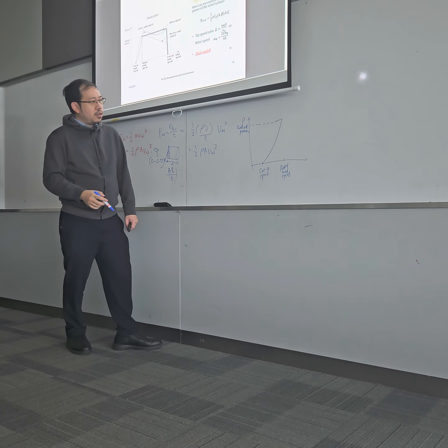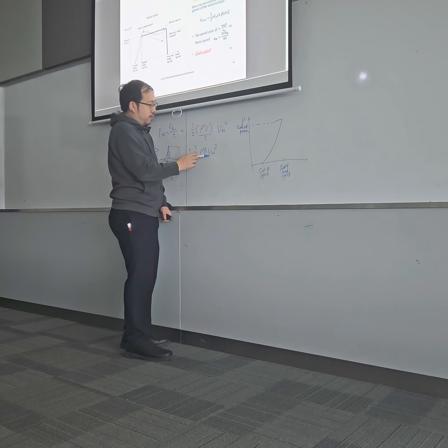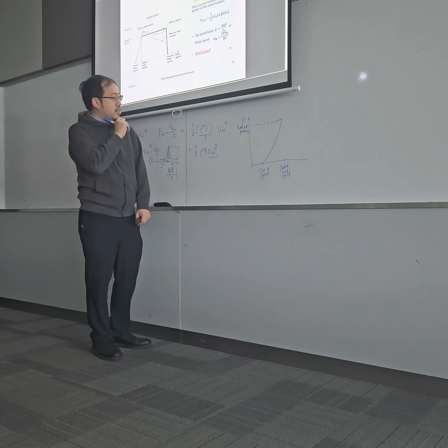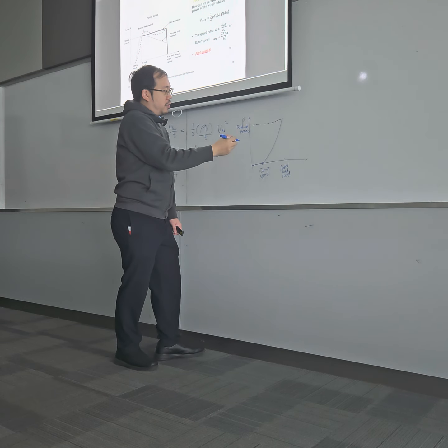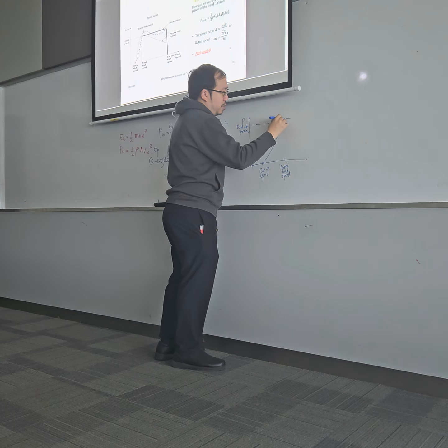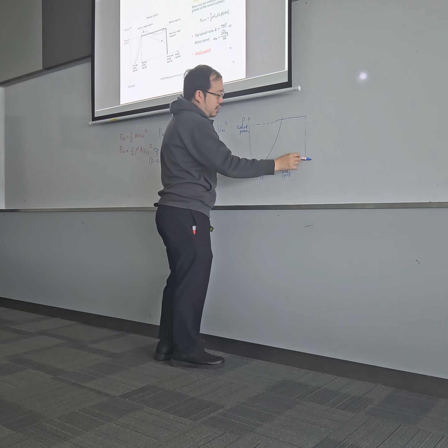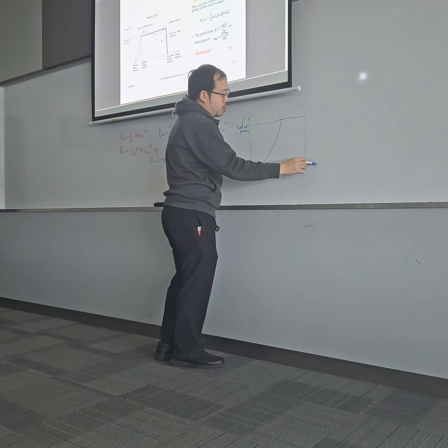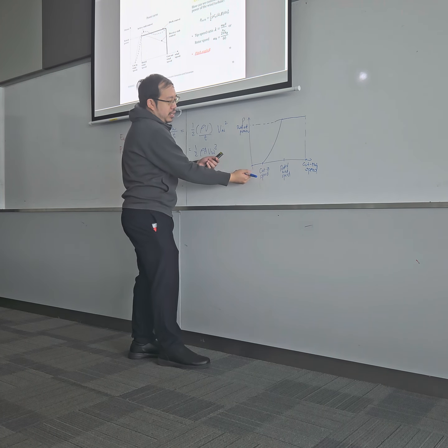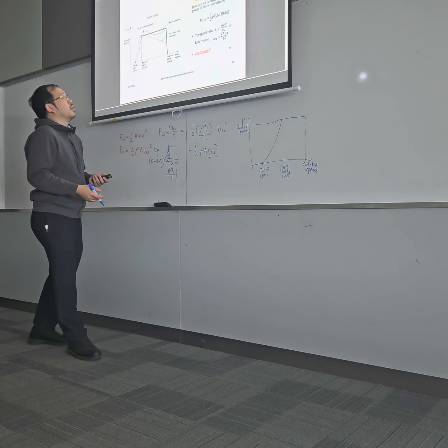Rated power. So it's exponential because this is in the form of V cubed, right? So it will have an exponential growth as the wind speed increases. And once it reaches the rated power, you would then curtail the output to limit it towards the rated power until the cutoff speed. So both before the cut-in speed and after the cutoff speed, the power is zero.